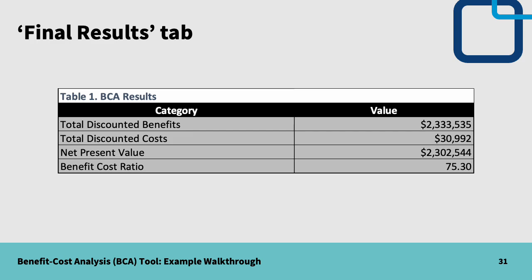And for BCRs, a value greater than 1 means that benefits are greater than costs. In other words, the project seems like a worthwhile cause. If the BCR is less than 1, then the costs outweigh the benefits. For component 1, the rectangular rapid flashing beacon is quite inexpensive, given its effectiveness at reducing crashes, so we've got quite a high BCR, making the investment more than worth it.